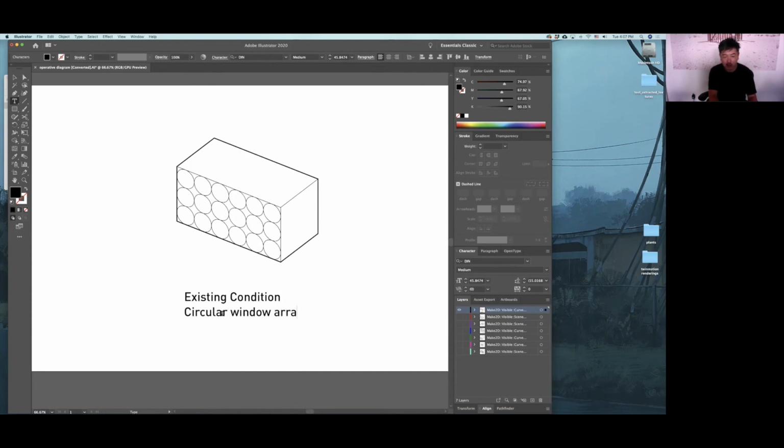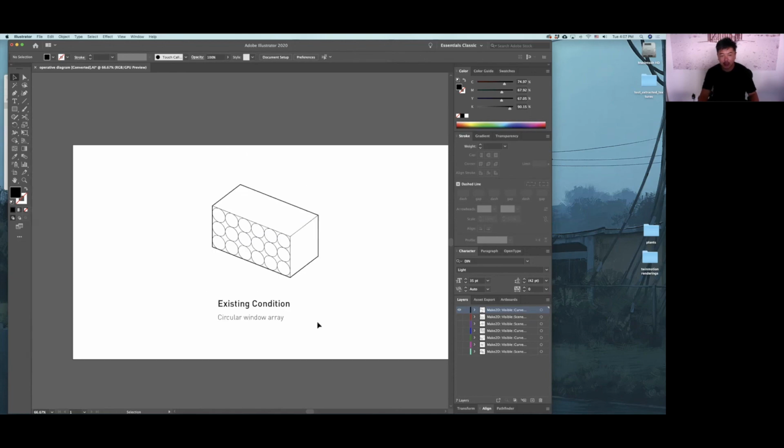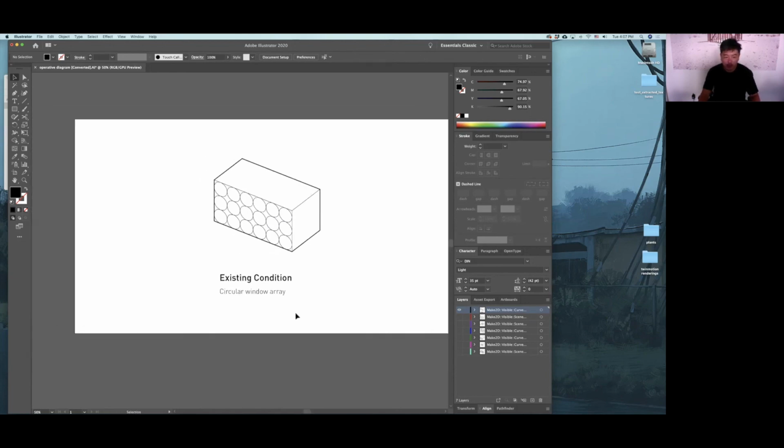Okay, so I am going to run this video faster at this point, and then just deal with the text. So that would be this. To copy this into another layer, you can select this way, copy, and click on the next, activate the next layer, and Command Shift Paste. That's going to paste into a different layer. Okay, it's going to go.